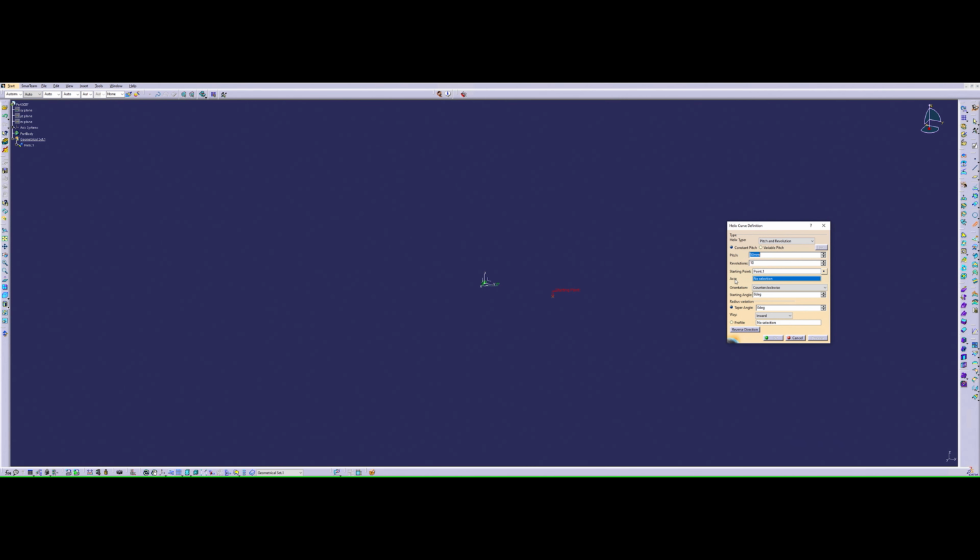So the axis now, this is quite obvious, I imagine. The axis is in which axis we want our design to be created. So, for example, if I push Z axis, my helix will start going up towards the Z axis. If I choose the Y, it will go in that direction.